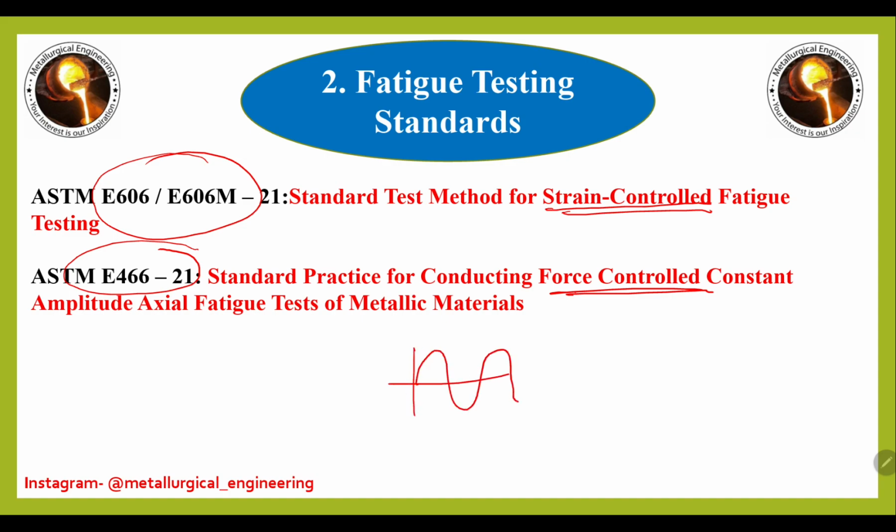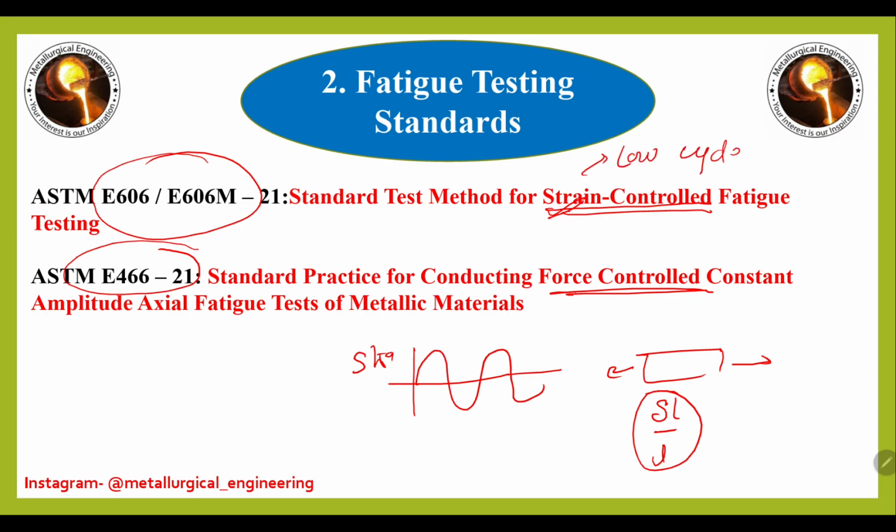As the name indicates, we control the strain, which is elongation, delta L by L. So we control the elongation, and it is mainly used in low cycle fatigue. And force control loading is used for high cycle fatigue, where we control the force applied to the specimen.